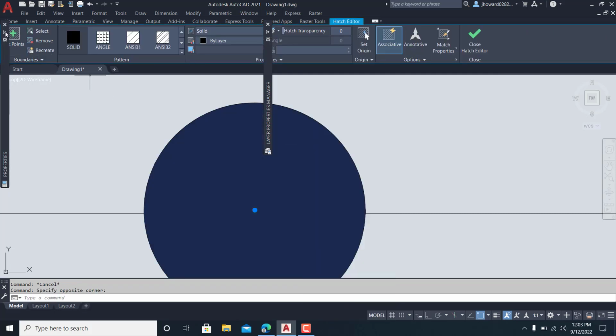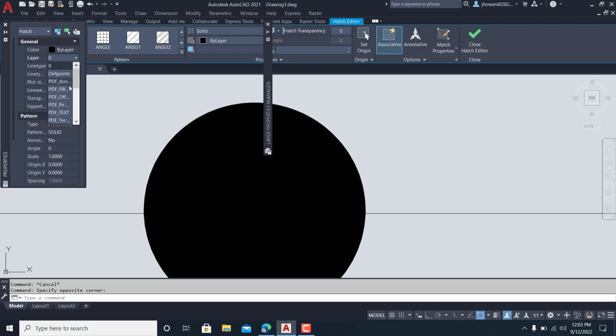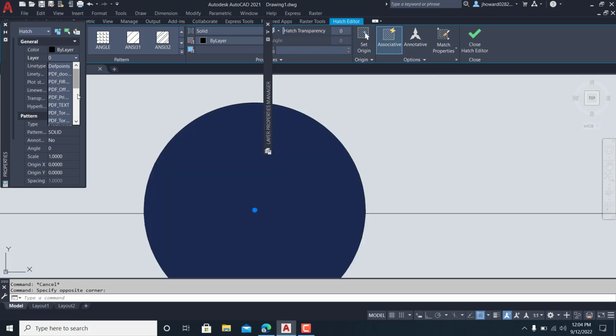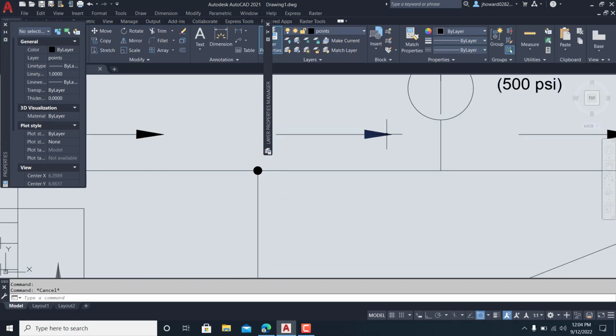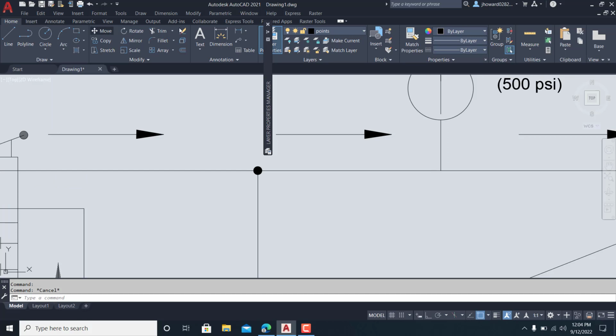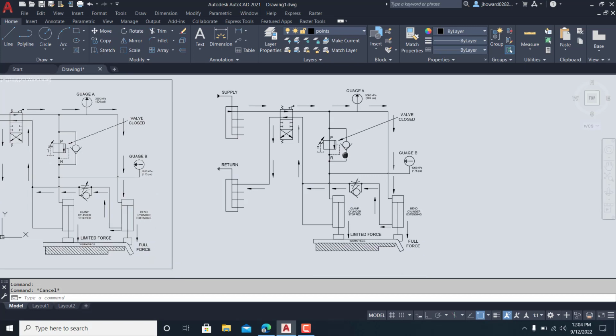from this point forward. And I've got my properties here. You could right click on it once you've highlighted it. And you can change your layer. It's on layer 0. I want it to be points. Okay, make sure all those are points and arrows. You might make you an arrow layer as well and put arrow or whatever this layer right here is, PDF 3. That's what I would make that hatch, so it all be together. That way in your PDF or in your drawing you can turn them on and off wherever you need to. Keep them all together makes it so much easier.